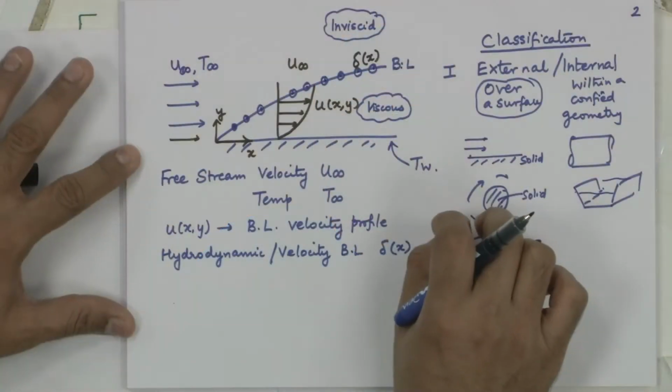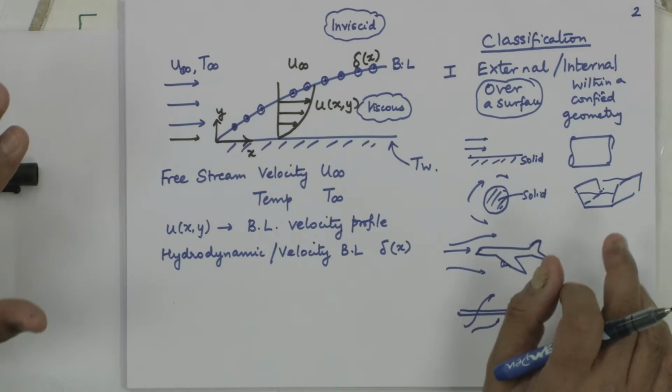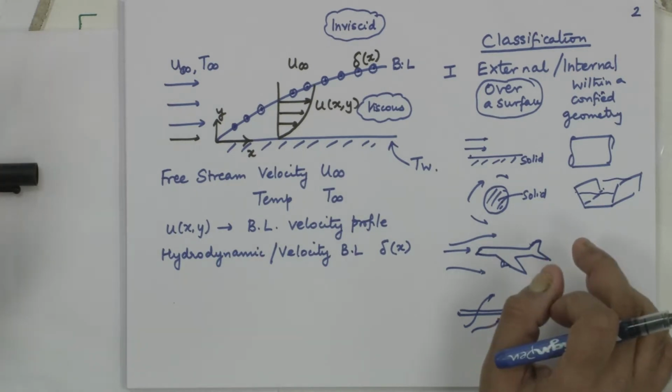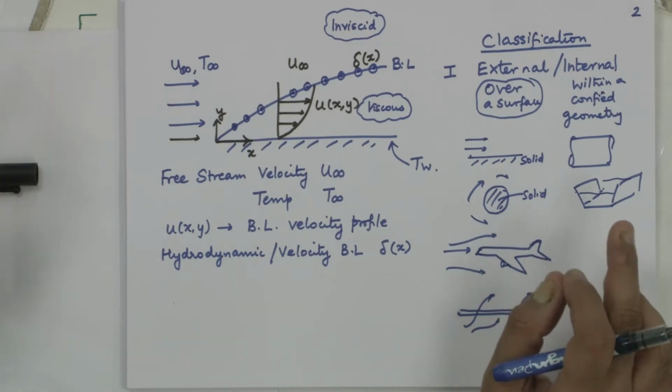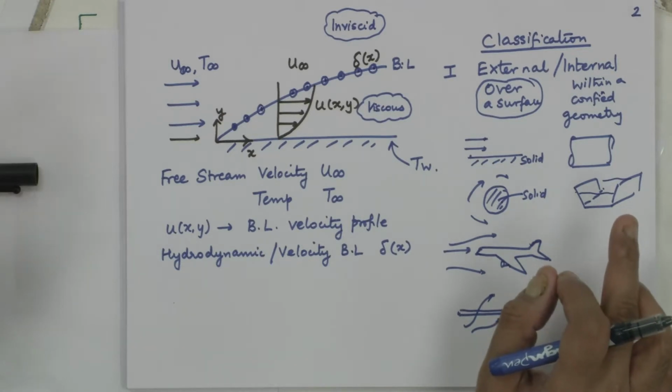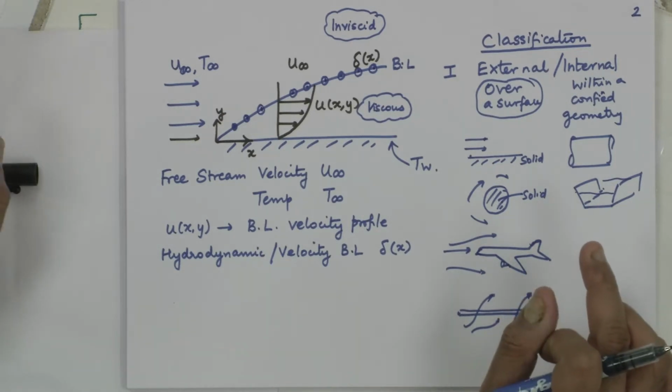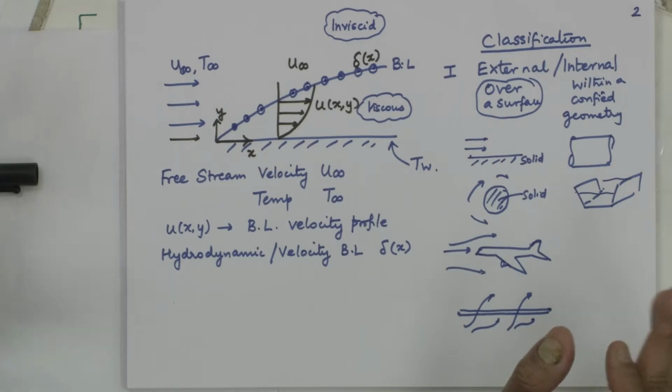Inviscid approximation, potential flow that you have studied in fluid mechanics, refers to an ideal situation. Ideal fluid flow, potential flow refers to a situation where all this behavior because of viscosity is not there. There is no effect of viscosity which is important. It does not mean viscosity is 0. Viscous effects are negligible in comparison with the pressure and the inertial effect. That is what you need to emphasize here.